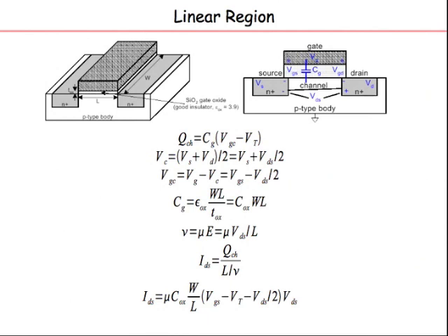You need to have what are called compact models, which are required for you to simulate your circuit. So the basic idea is very simple. For any particular potential at all the nodes, you find how much charge is there. That is the most important thing. You have to calculate the charge, because current is the rate of flow of charge. Once I know the charge, I can calculate the current from there.